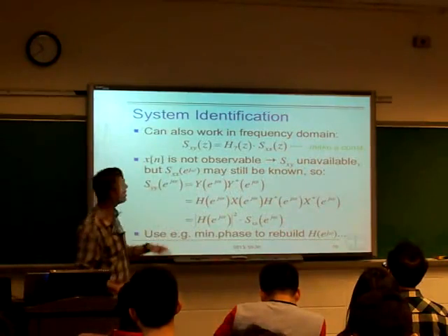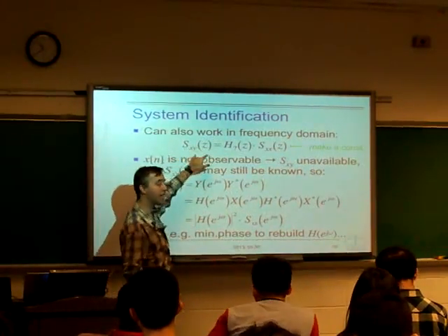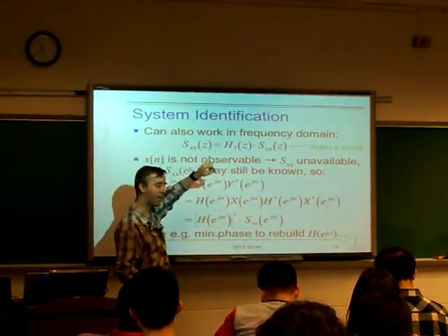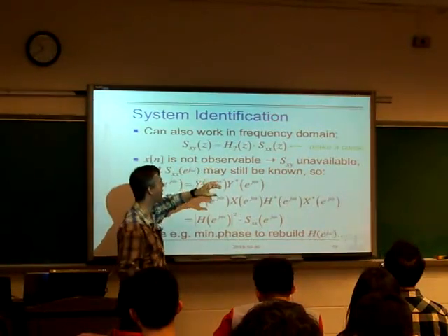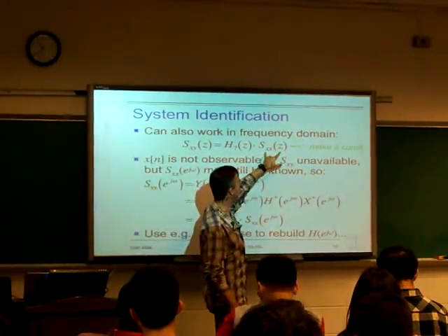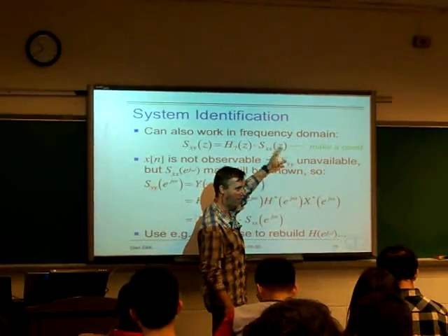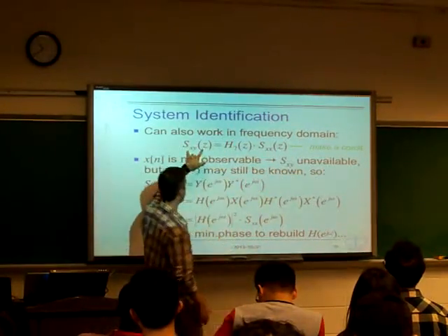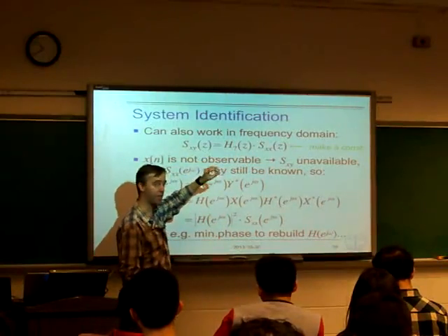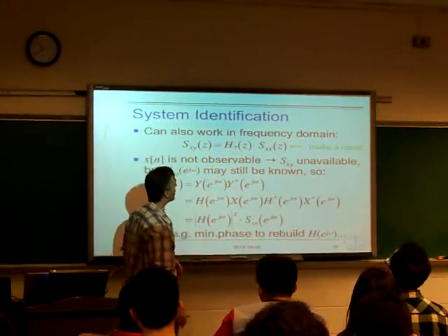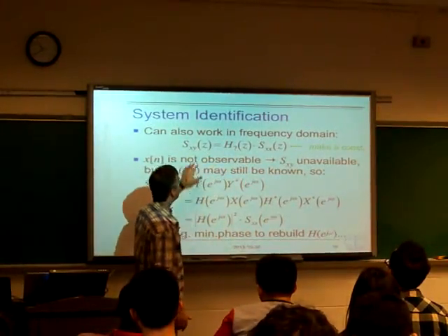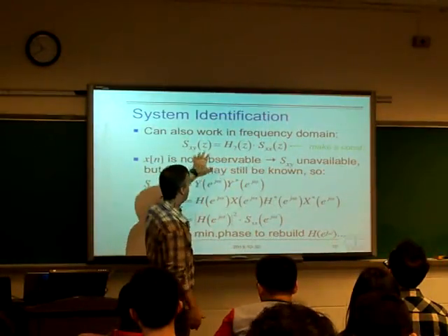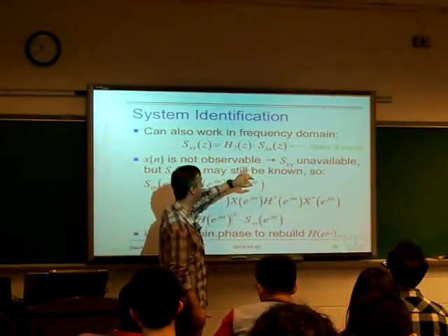So we take the Z transform of that. The Z transform of a correlation is a power spectral density. The Z transform of the autocorrelation is the pure real power spectral density of X, and this is the cross power spectral density of X and Y, which shows both the total energy and the phase change between them. And so again, the convolution becomes a multiplication.